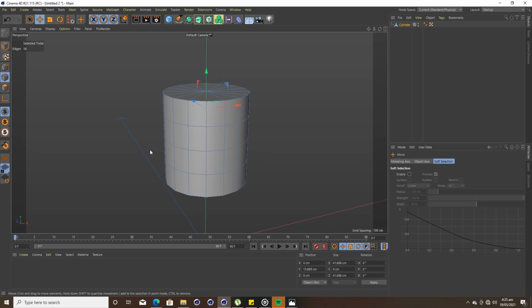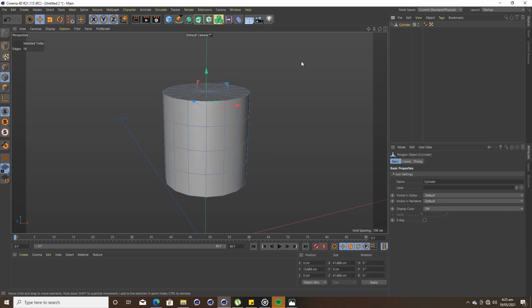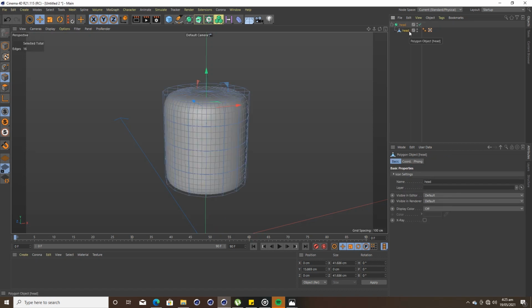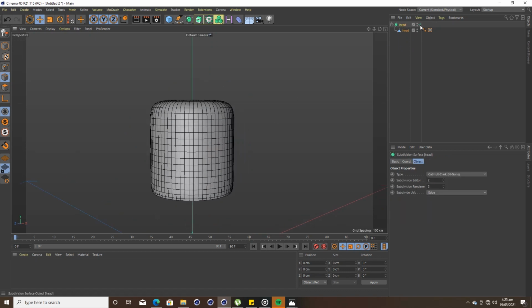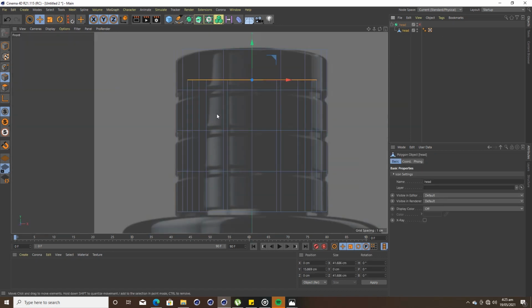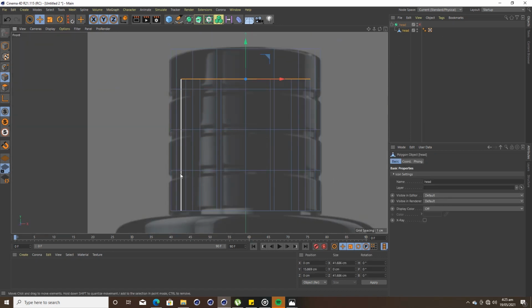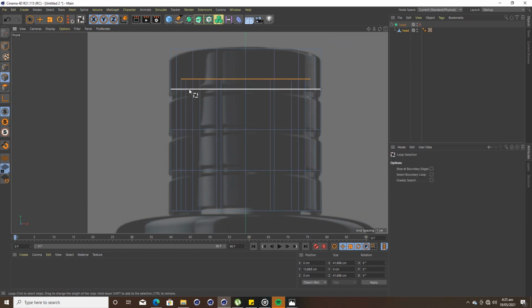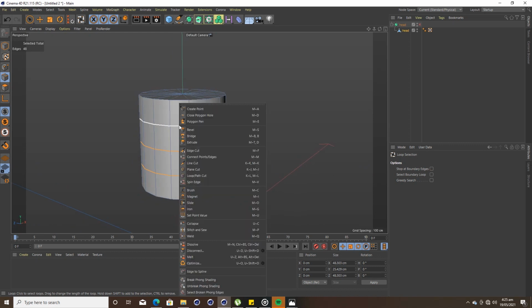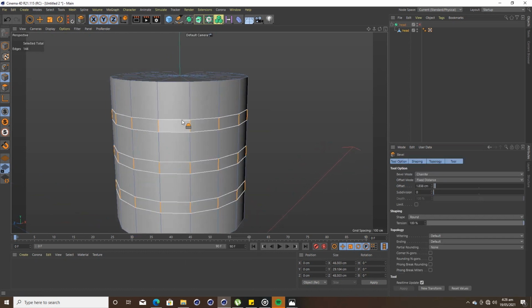I'll go back to my front view, but before I do that I'll create a subdivision surface, drop this model in and name this head. I'm not really good with names, but hey, I'll call it head. Okay, let's deactivate that and go back to the front view and loop select these edges where we have the extra detail. Don't forget you can use U L on the keyboard to select that, and I'll right click and select bevel and bevel those edges out.